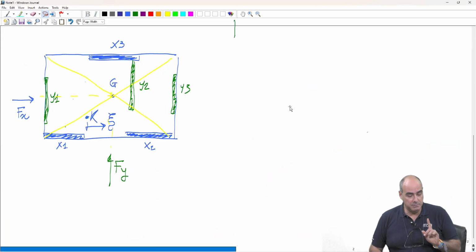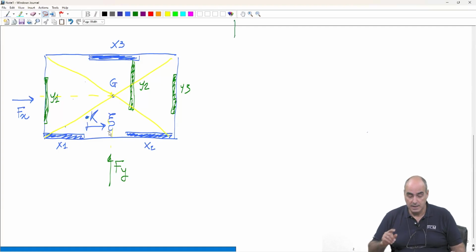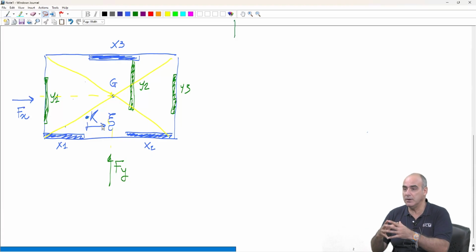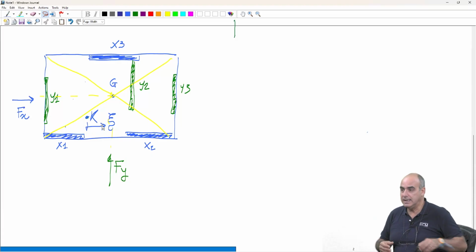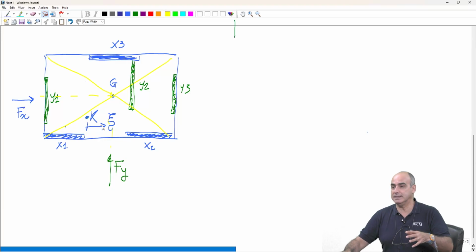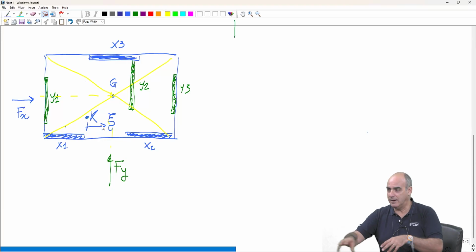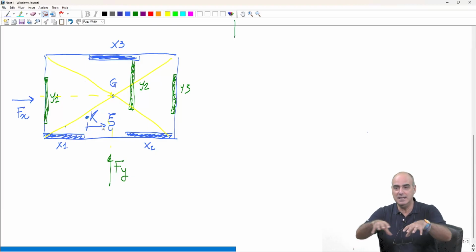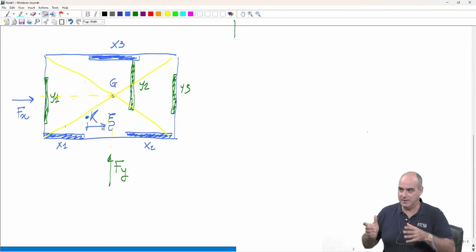Now, what we have done before is that we have only considered the effect of the force. But as I said, the system, when it reacts to a system of lateral forces, does not react along the center of gravity, because you have to imagine that the system is made of discrete rigid masses. Have you seen those desk toys that are made with spheres connected? It's like that. You can imagine a series of discrete masses which are virtually connected by the diaphragm.